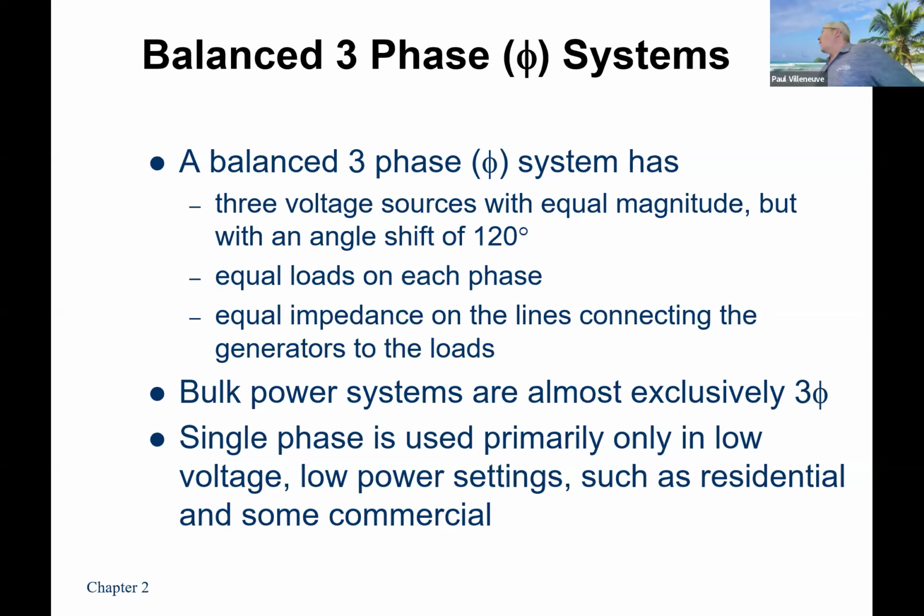And so almost exclusively, almost the entire power system in the entire world, not just in the US or North America, in the world, is run with 3-phase. Exceptions: DC systems, right? We already talked about the high voltage DC systems that now come into Maine, and there's also one in Mass. There is a 6-phase system in Africa. I think it's in South Africa, but it's a very limited application. There was a trial one set up in New York to do some research, but it never really went anywhere. So almost every system you'll ever come across, even if it's a medium power system, is going to be 3-phase. Like coming into campus, at the top and bottom of campus, those are both 3-phase interconnections.